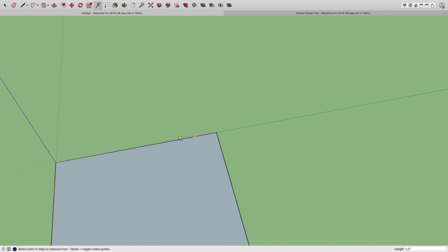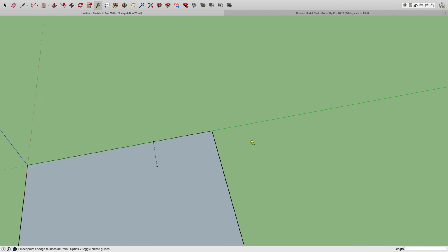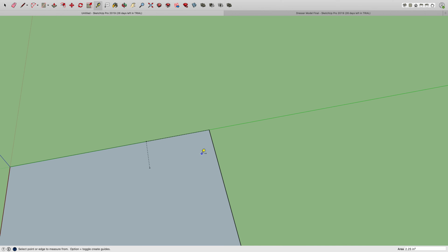And then we can also do the same thing here. And if we click and move this way on the red axis here, you can see if you hold down shift, it'll sort of constrain it. And this way we're going to come in 0.25 inches and hit return. And that sets a little gauge there. So this is ½ inch in and ¼ inch this way.